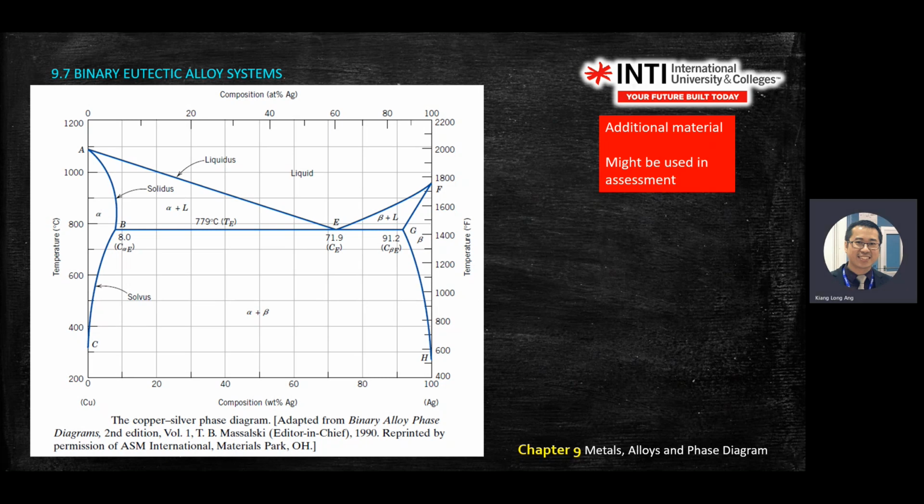Then the eutectic temperature, the equation, how you write it, is from liquid to form solid, right? Left pocket, right pocket. So the far left, you get alpha. How many percent? Drop down, write the percentage of the Ag. Beta, how many percent in beta of how many percent of Ag? Okay, that one is the equation that we're looking for, the eutectic point, right?